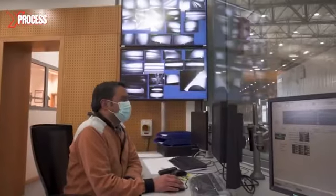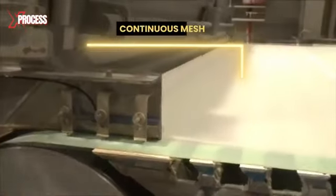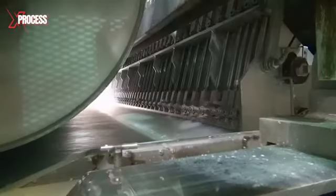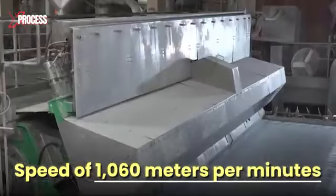The paper machine consists of a series of sections and screens, and the pulp is poured onto a continuous mesh, allowing the water to drain and the fibers to interlock to form the sheet. The water is extracted with this equipment, which operates at a speed of 1,060 meters per minute.